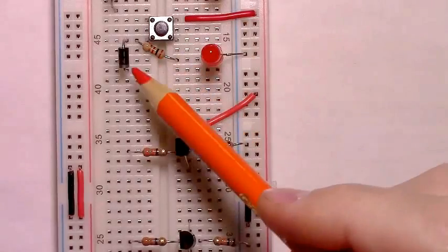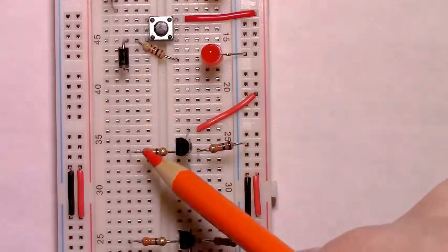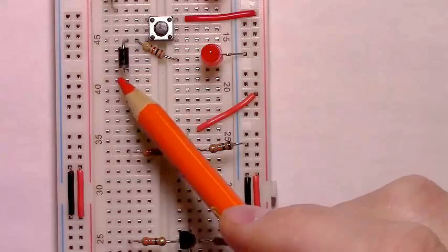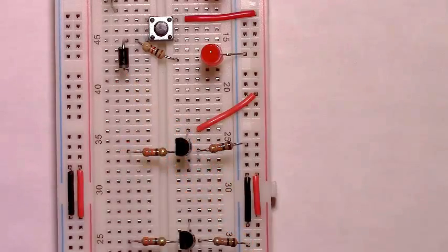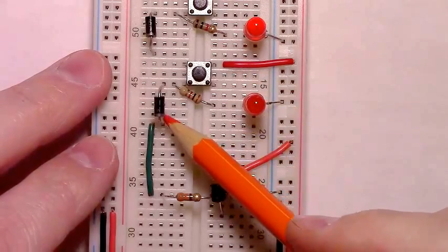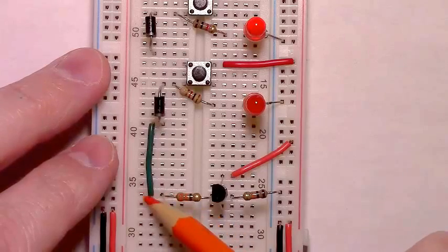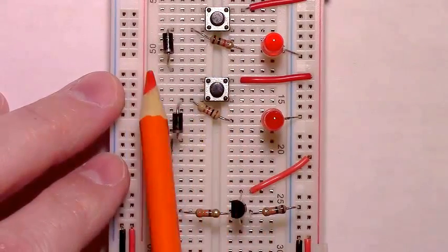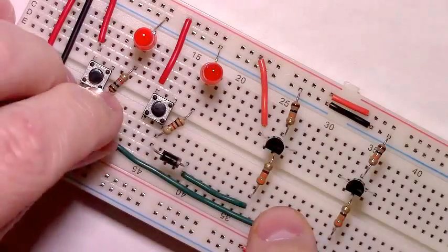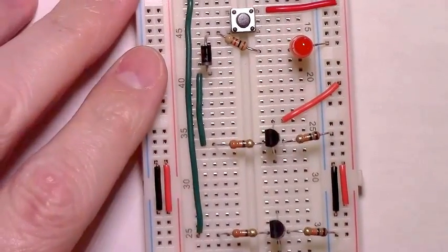First thing we'll do is add a piece of wire from the rail that the cathode of this diode is in, down to the rail that this leg of the 330 ohm resistor is in. We'll just run a piece of wire from here to here, like that. It's connecting the cathode of the diode to this leg and this rail with a 330 ohm resistor. We repeat the same procedure from this rail down to that rail, like that. Zoom out a little bit.